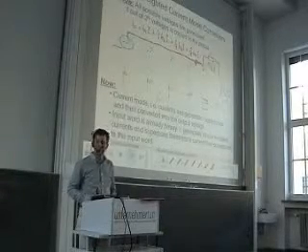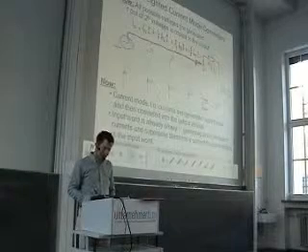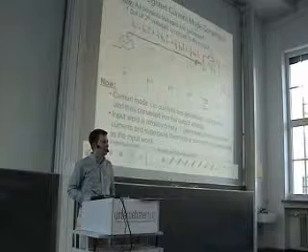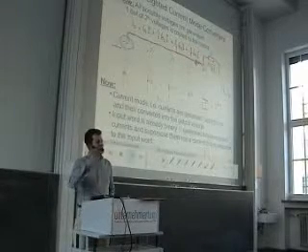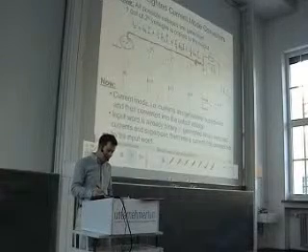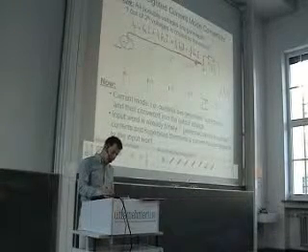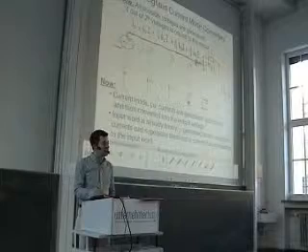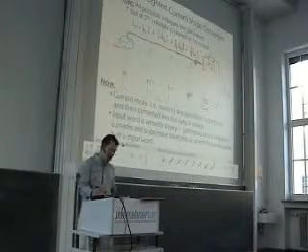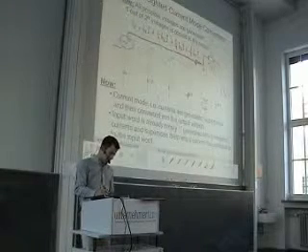Yeah, we have a 4-bit structure, which means that we would require 16 resistors or 16 switches in a resistor string case. Here you see we have only 4 elements, but these elements are binary scaled. So what is a disadvantage of this?